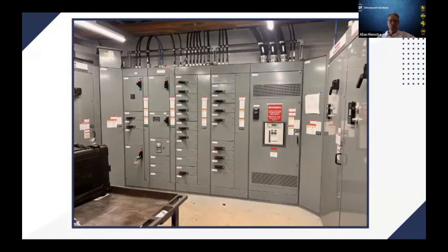But the question is, where is it? Which one do we open up? Well, the easiest way to do this is to take a contact ultrasound sensor. Remember, at the beginning, I spoke about the way a doctor uses a stethoscope to listen to our chest and our lungs and our heart. Well, we're going to listen to the heart of this switchgear panel using the same methodology. We're going to put a magnetic contact probe on the panel, and we're going to take a decibel reading in the ultrasonic range to figure out where the loudest point is coming from.